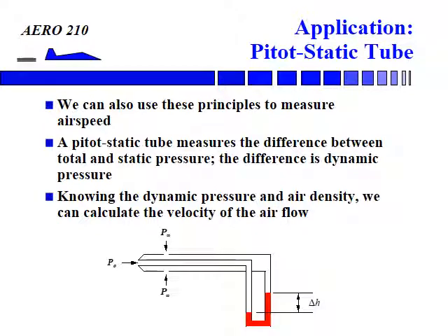And we can measure static pressure with those ports because they're parallel to, rather than perpendicular to, the airflow, and hopefully the velocity is approximately equal to free stream velocity. If we connect the static ports to the other side of the manometer, then the difference in the heights of the columns in the manometer is proportional to the dynamic pressure, and that we know is proportional to the velocity squared. And that's one way to measure velocity of an aircraft.